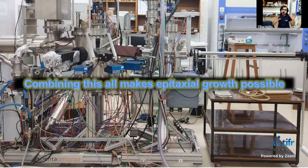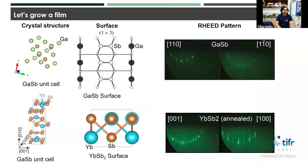So combining all of these methods makes molecular beam epitaxy possible. Now we'll demonstrate a growth of our thin film live. We have a gallium antimony substrate, and we have prepared the surface. The surface looks like that, and the corresponding RHEED pattern looks like that. We'll try to grow YbSb2, which has this kind of crystal structure, and the surface looks like that, and the corresponding RHEED pattern will look like this. So we'll try to grow that.